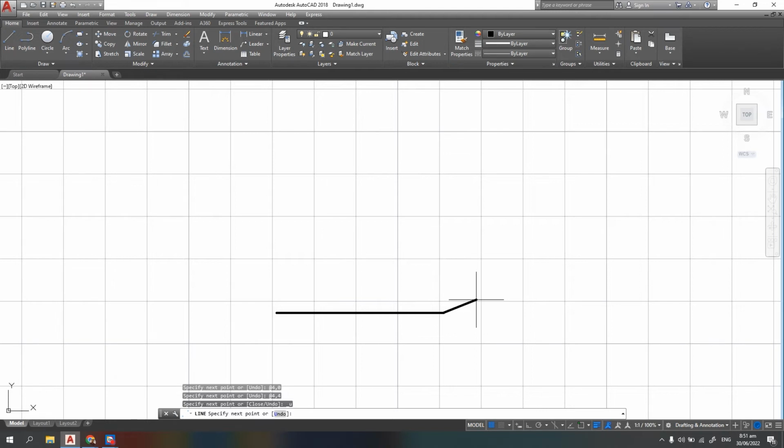But in the second method, your first point of entry, or your origin, will always move. Your assumption of 0, 0 will always move to your last point of entry. Okay, so it has an advantage, but if you are a beginner, you will get confused when mixing absolute versus relative coordinate entry.